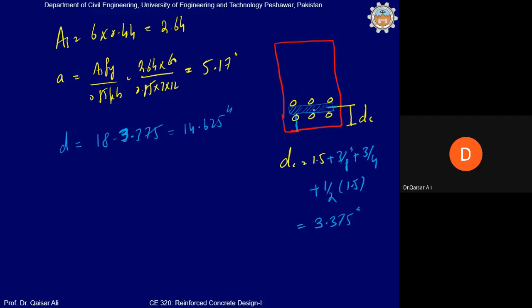We can give this spacer at, for example, 18 inch or 24 inch center to center distance. Clear? Yes sir, clear. So about this spacer, you will provide it in the second layer. If there are two bars then it is not needed, because you can bind those bars with the stirrup legs. Clear?